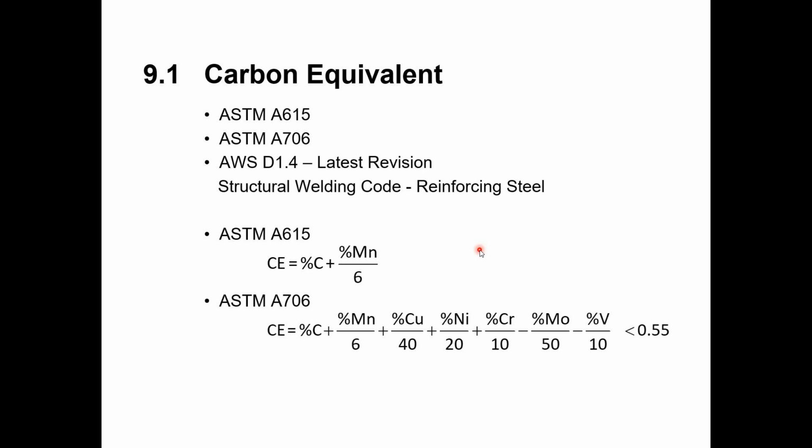So it's giving you a caveat there that only 50 degrees is required for up to 11 inclusive, and then for number 14 and 18, you have to at least heat it to 50. But for either of those, if the ambient temperature, which you would assume the base metal would be if it's just sitting out in a rack, is 32 degrees, it has to be heated to at least 70, just to make sure that you don't end up with that rapid cooling.